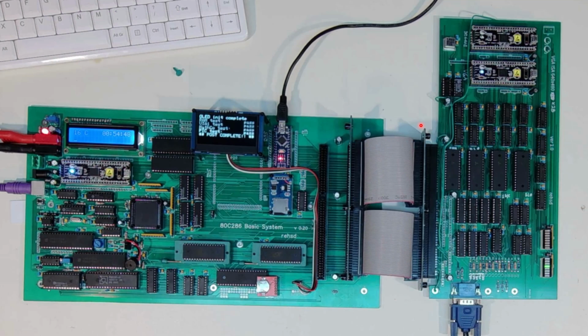And so here's a picture of my 286 system on the left and a video card that I'm working on on the right. And you'll see that on the 286 I've got a PSoC just put right onto my system board. And at some point, maybe I'll take that away and actually put on discrete chips, but I'm finding it so handy just to be able to change and adapt my system.